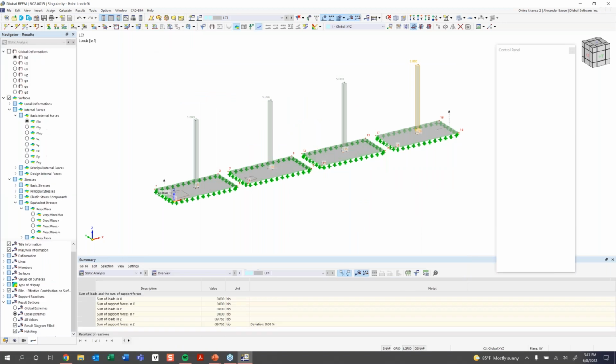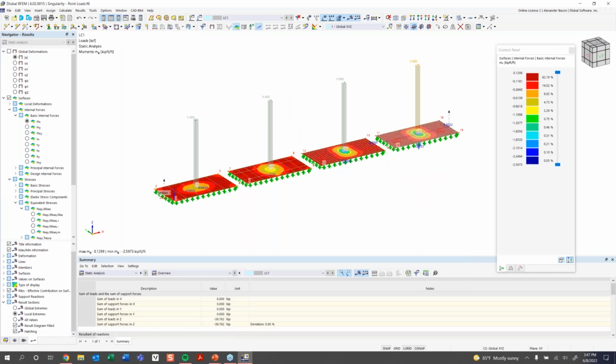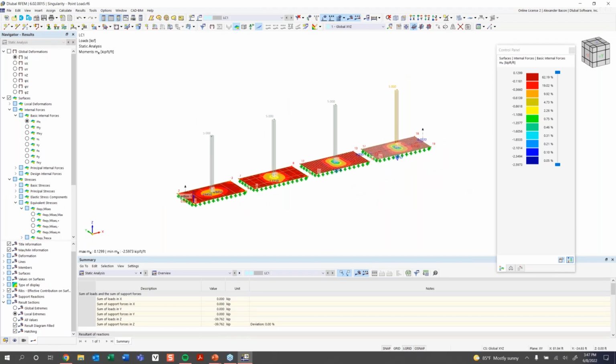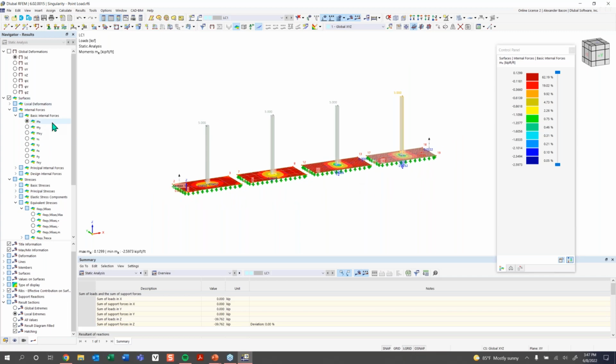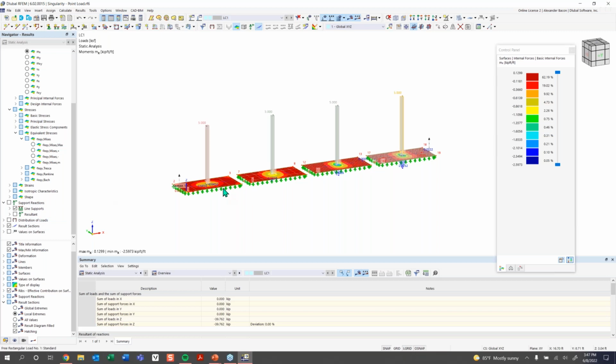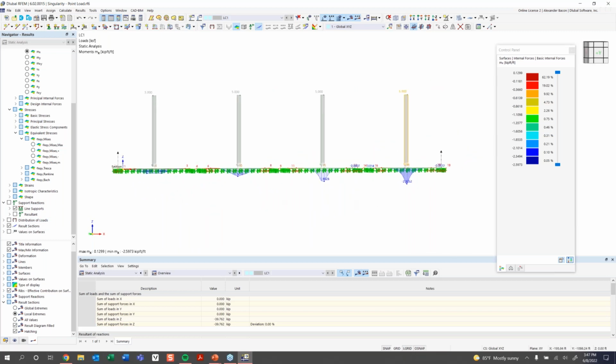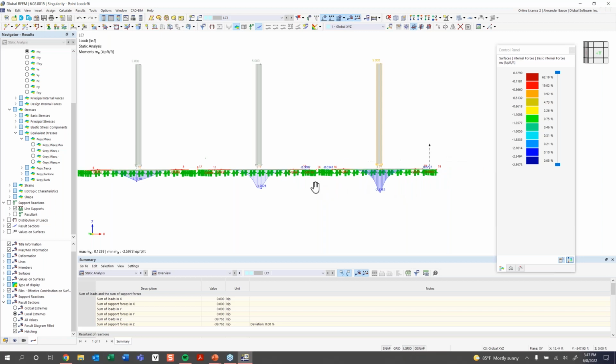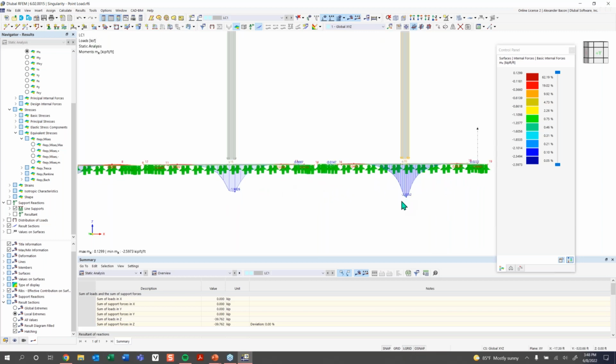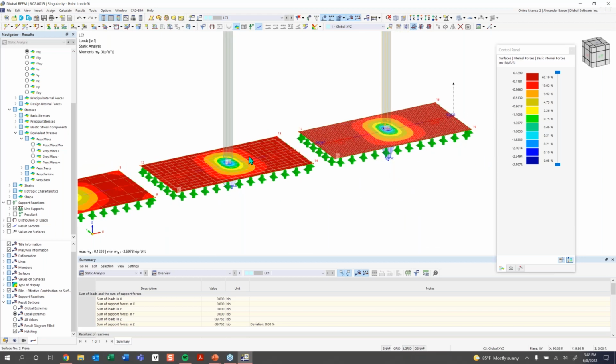And this calculation will run. And so now we can take a look at our moments here. We got to activate, take a look at our moments here. So now we're getting no singularities because at every surface here we have similar moments. So it's not as drastic a change, but you can see between these last two surfaces, 1.9 and 2.3, definitely a lot better than before. And this is one of the ways you can combat point loads when they cause singularities.